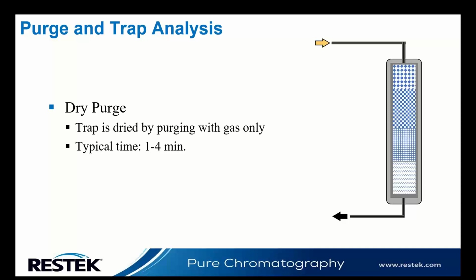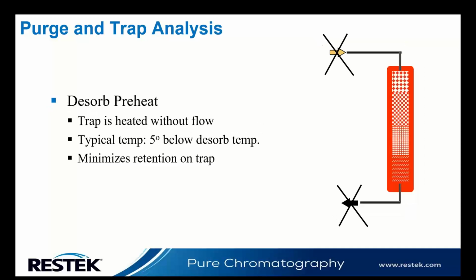I've found that a 1 minute dry purge is more decoration than anything else because it doesn't do much. You generally have to go with a longer dry purge. 2 to 4 minutes would be more appropriate than what we have on here, the 1 to 4.